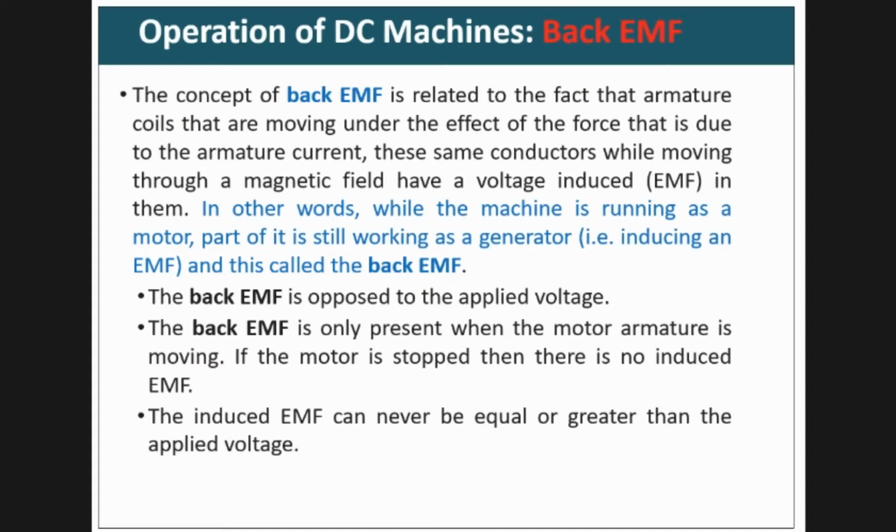So the back EMF is opposed to the applied voltage, and the back EMF is only present when the motor armature is moving. When it is steady, then there is no induced EMF. The induced EMF can never be equal to or greater than the applied voltage.